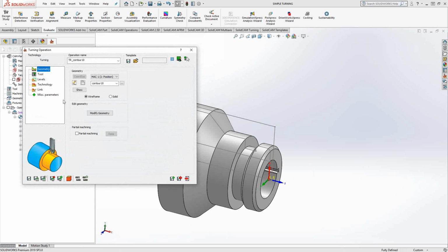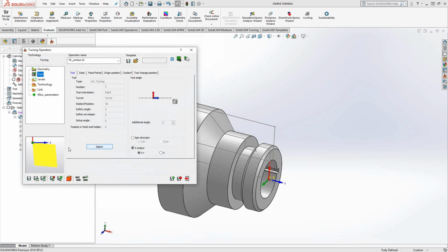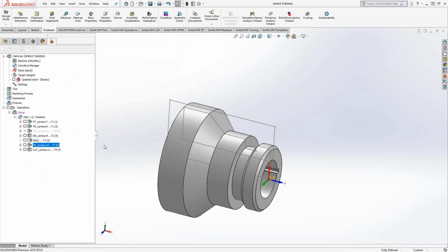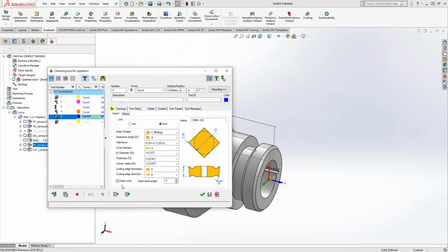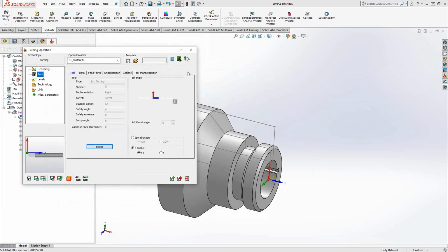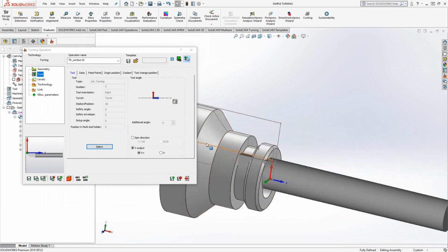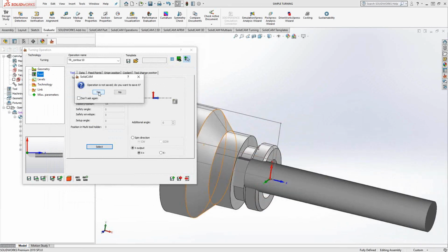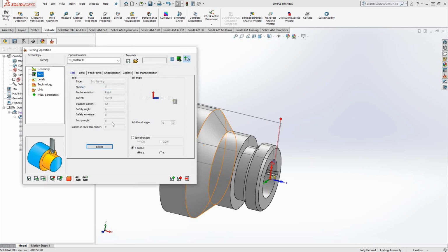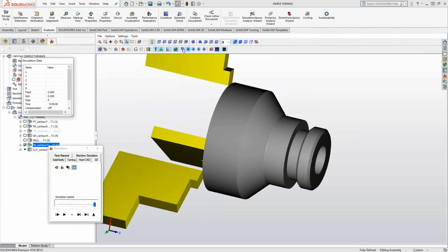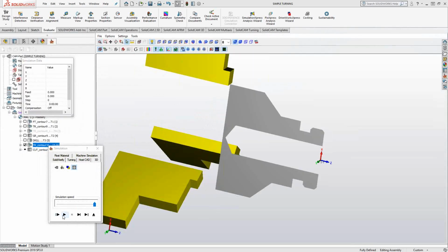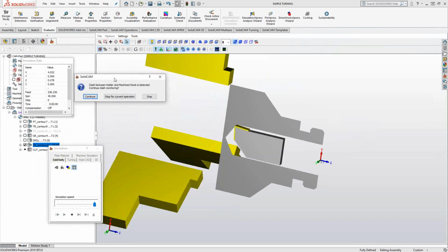If we open that up, I actually went ahead and made it insert only, because I wasn't looking at the shank. I didn't want to check the dimensions of the shank, but this time I'm going to do that. And if we do this, we'll notice that this thing is probably too big for my bore. Okay, so what happens when we SolidVerify that? Okay, let's put that back into 2D and let's play that through. And it's giving me the error message.